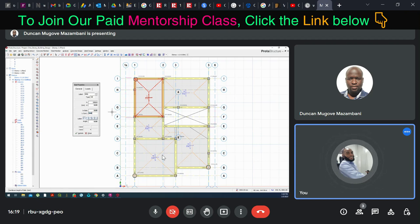Then on the loads, click on the load tab. There is what they call cantilever load. You can see that we have parapet load now. That parapet load simply means cantilever load. As I showed you before, cantilever load is at the edge of the cantilever, as I showed you from the beginning.